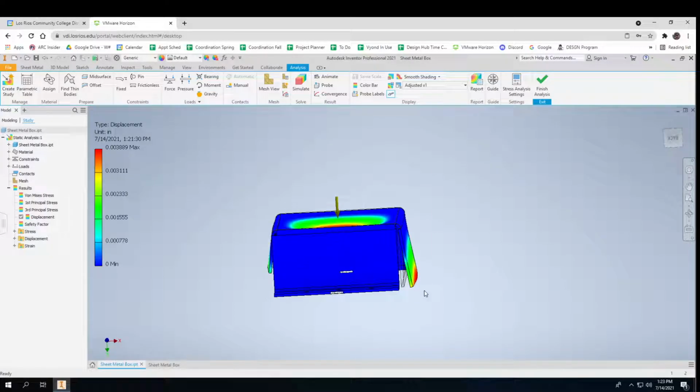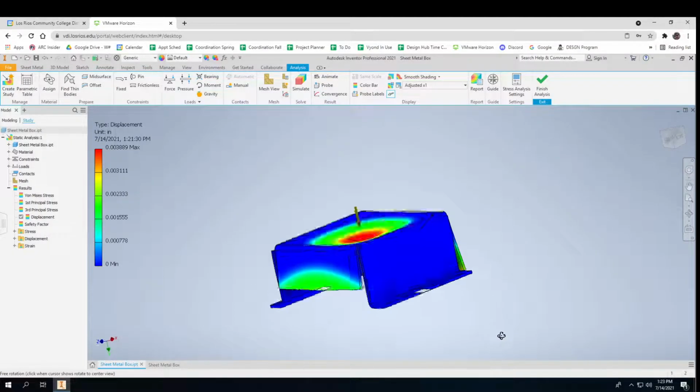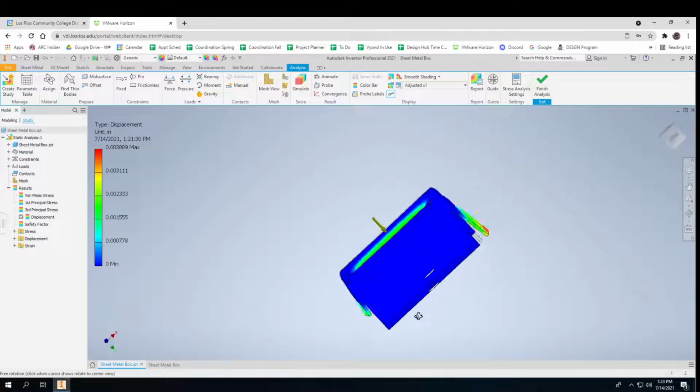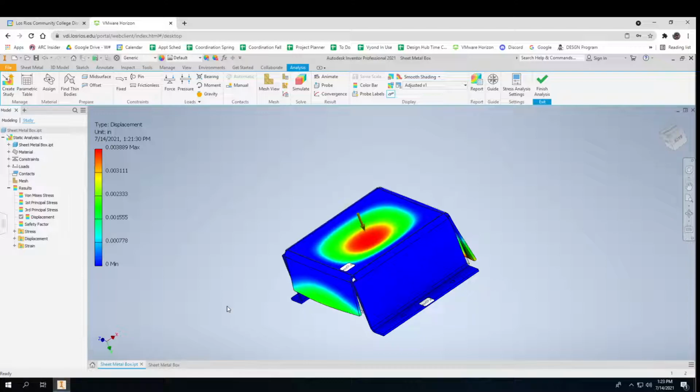And so if that wasn't acceptable to you for some reason, you would put a flange on there too and bolt it down. Or you go, oh, that's going to scrape and hit something, I'll make that some tiny bit shorter or something like that. So it's really not deforming as much as you think it is from here. It's showing you a wildly magnified version of it.